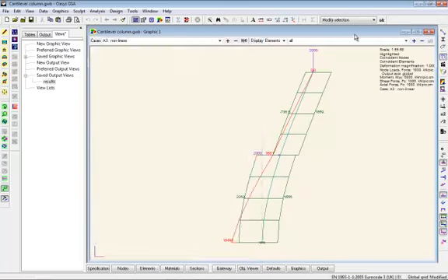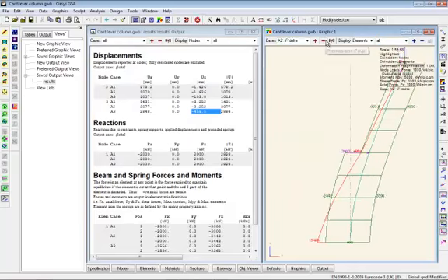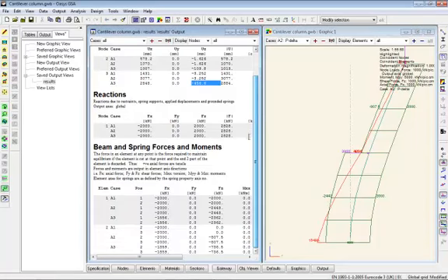In some respects, because the P delta analysis is not giving us a proper rotation, it's just giving us axial shortening, not the rotational effects. The P delta is structurally deflecting too much for the P delta analysis to actually give us sensible results. Whereas the non-linear results are much more sensible looking.